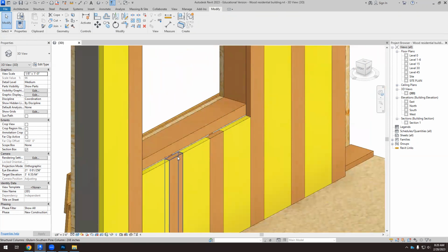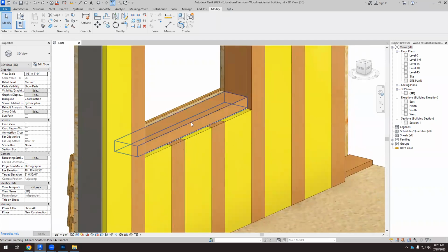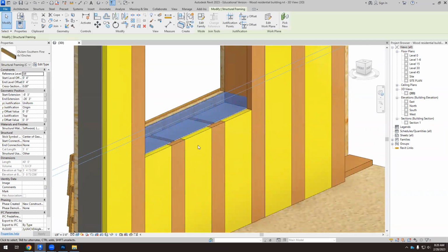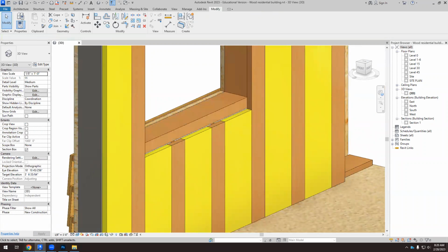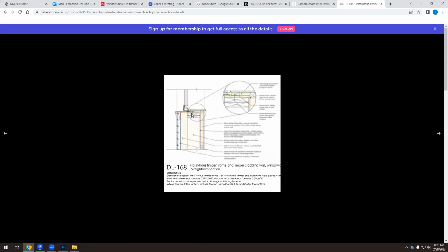I told you that the first decision that I was going to make is whether we cover this beam with thermal insulation or not. So apparently in that detail, they have covered that beam. Well, here they have two elements. We had only one, but they have covered this with this yellow thermal insulation. Okay, so that's what we are going to do.